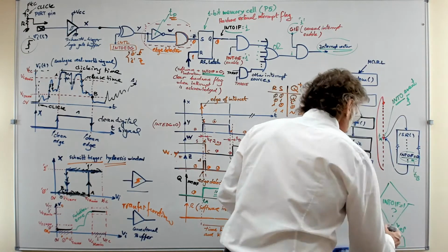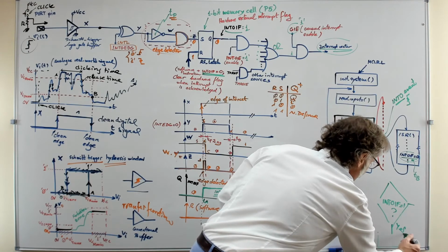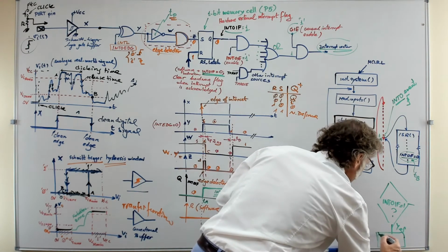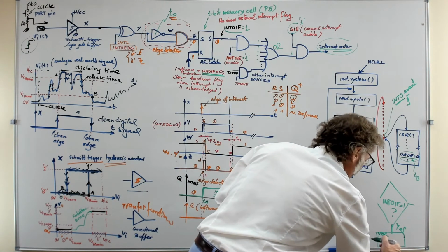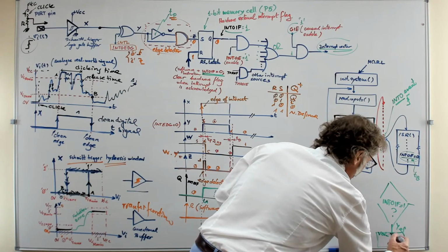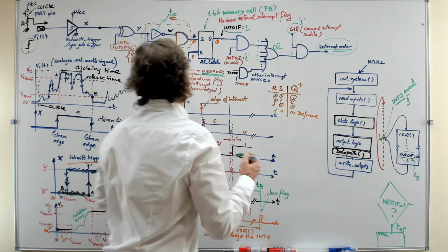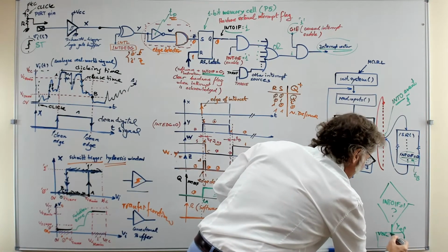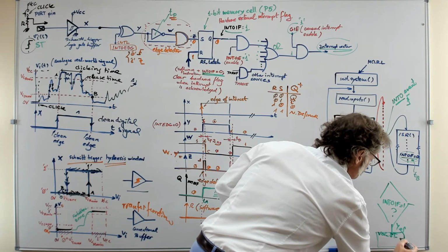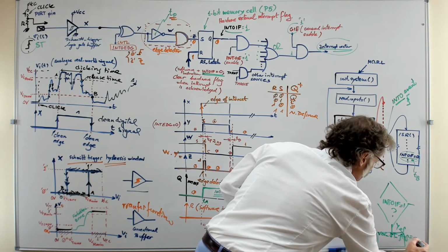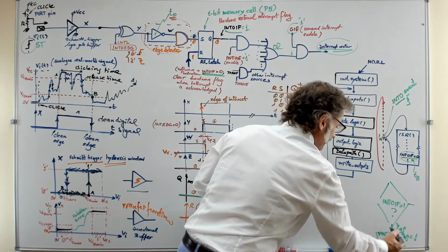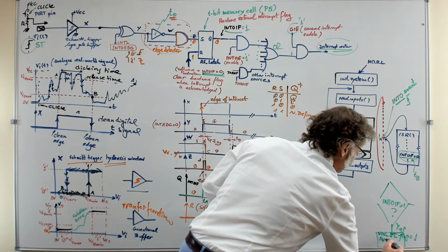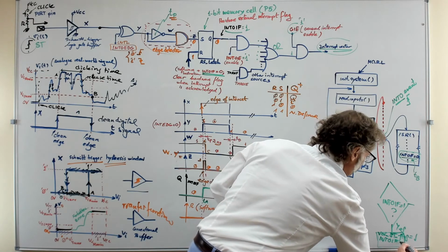For example, here you will set, basically what we do in this introductory course is very few things. We will set the software variable, the bar. For example, if this is a clock, or if this is the start button, we will name that bar start button, or start transmission flag. We will set that variable here, and then we will clear the hardware flag, the int0 interrupt flag equals 0.